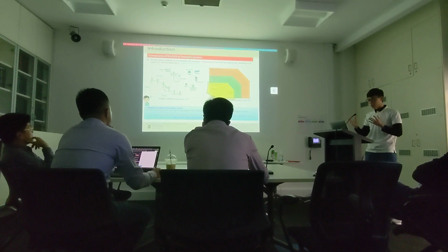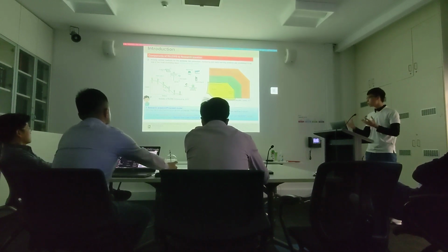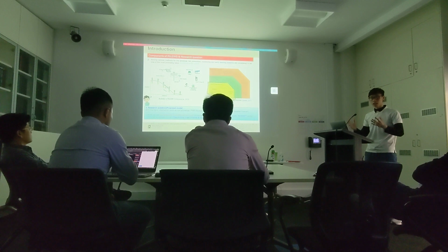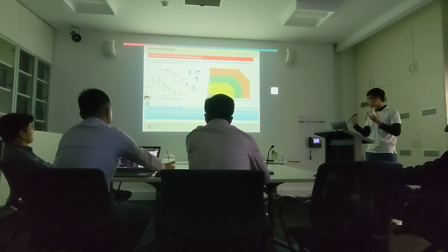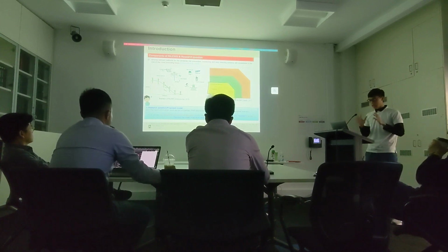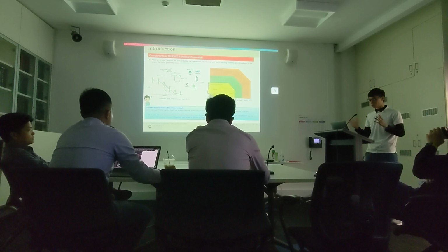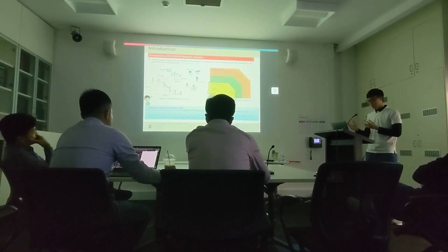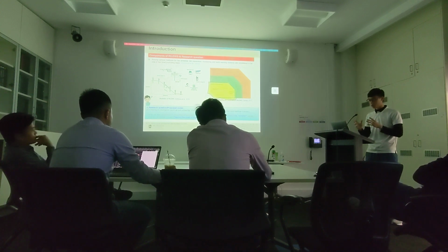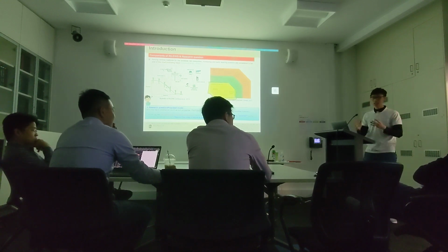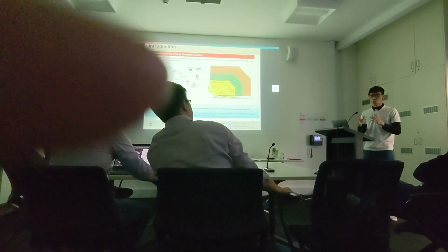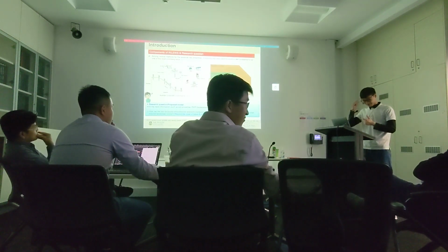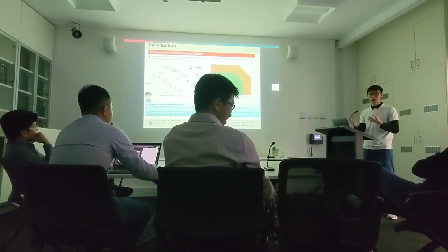With the input information, such as soil properties and water pressure we get from sensors, we generate the initial condition, and with the rainfall data we get from the rain gauge or from weather forecast, for example 2 weeks ahead, how can we use an advanced computational approach that can predict when, how, and where that disaster occurs? Here we want to emphasize the information beyond the onset of failure. It means that we can detect when the failure happens, and we also want to know the destruction zone and its impact on the community.